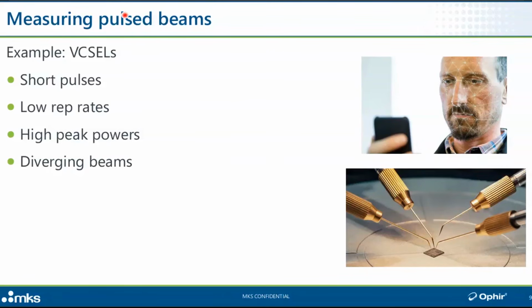Unlike the more standard, more classic edge emitting laser diodes, VCSELs emit upwards. And so they can be easily packaged as an emitter array containing hundreds of emitters on a single chip. They can generate powers from milliwatts all the way up to a couple of watts. Some unique properties: because they're tightly packed, they would need to operate at very low duty cycles, meaning short pulses and relatively low frequencies because of thermal issues. Otherwise, they're going to overheat. For some applications, this is perfect.